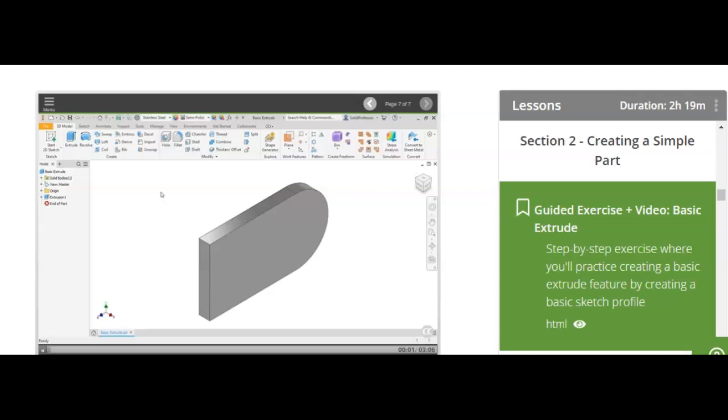As with any design in Inventor, there are often a lot of approaches that will lead to the same end result. Even a simple design like you see here could be accomplished with a variety of approaches, but I will walk you through just one of the ways here. Regardless of the approach, one of the goals here is to fully constrain any sketches. And we are also looking to have the part match the orientation shown in isometric view.